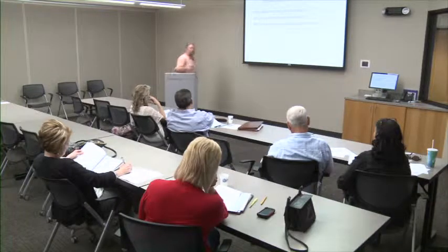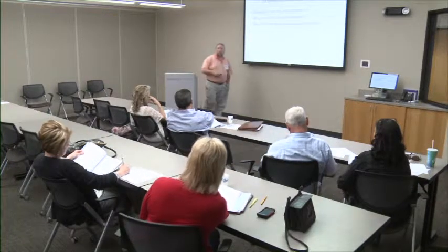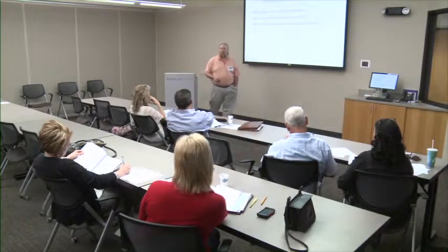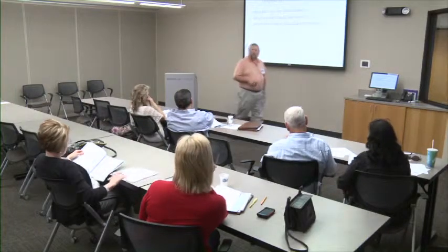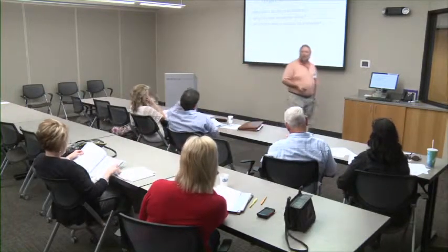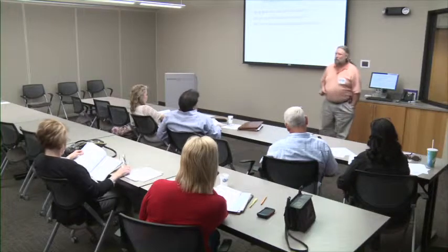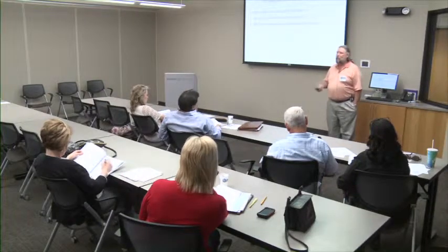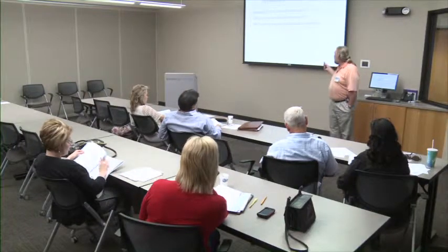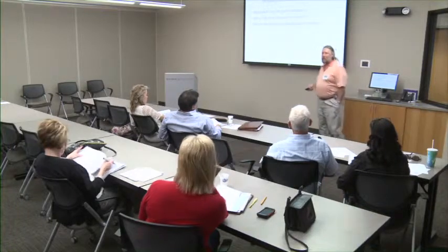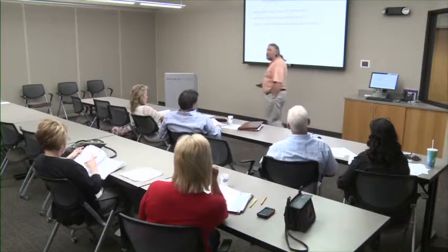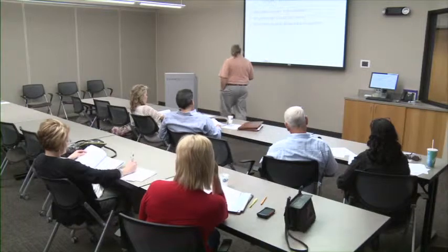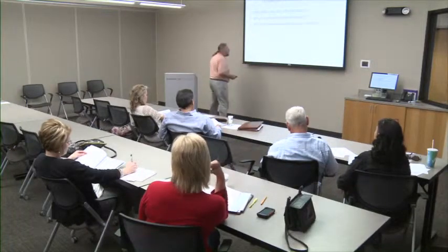For our owner, we may just give him a weekly summary of what's going on. For our foreman, we may have a day-to-day schedule for him that has what's going on each day. We may even have a schedule for him that's an hourly schedule because that's what detail he needs. So who's using the information makes a difference on what we put together in the schedule.